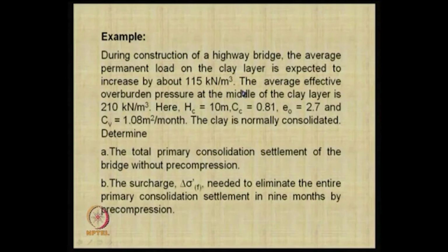So, at some point, say for example, you have 10 meters of the embankment, you will be able to calculate stresses at every 1 meter level. What is the extra stress because of the embankment construction of 5 meters? It could be very high, but as you go down, the additional stress that you can expect from the load is less, like the twice-the-breadth pressure bulb concept.